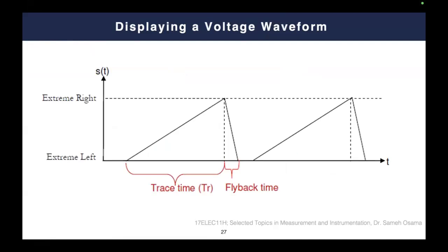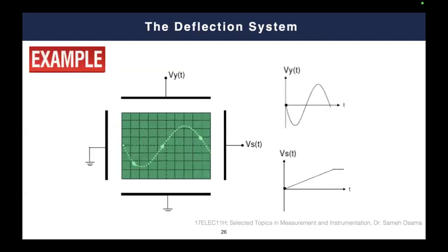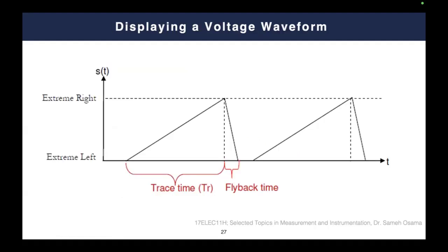First, you will tell me a very simple question. That's not only to make it at once. So it's a periodic signal. We have to make this triangular, or it's typically a sawtooth. We have to make this sawtooth signal in a periodic way. That means that we have to have this triggering signal in a periodic way so that you can plot a cycle, a second cycle, and third cycle. So that's why we have this continuous vision on the oscilloscope. It's a running sinusoidal. It's not only one screenshot. So we have to have such a signal.